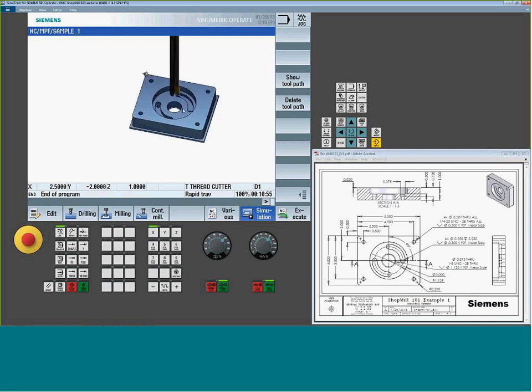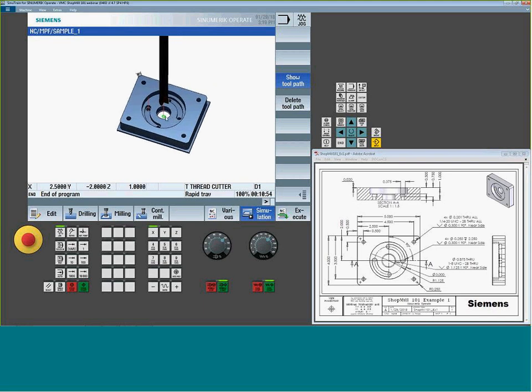You won't actually see the teeth per se of the thread, but you will see the tool path. So we can show the path on. If I cleaned it off, you'd see just the little helix that the thread mill does. We can start it one last time to show you. Okay, so it's going down, cleaning things up a little bit. Just jumping a little further. All right, so there is my slots, and there I go. There's my little path in there.